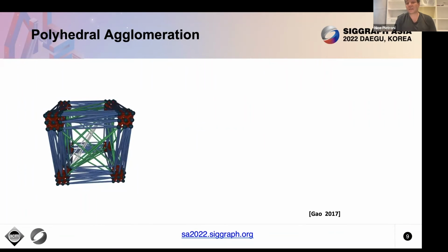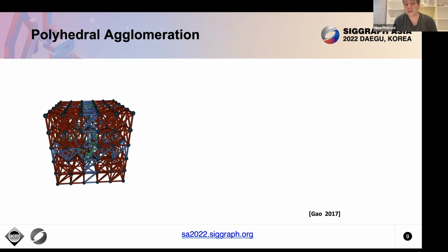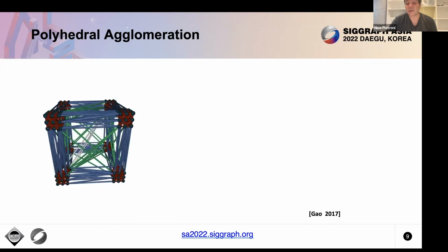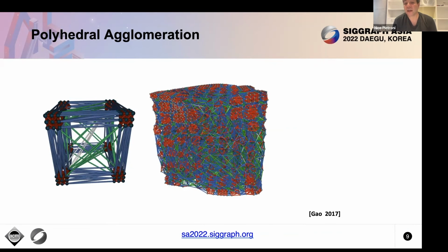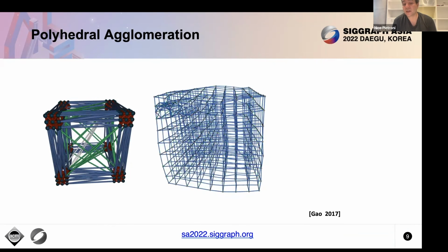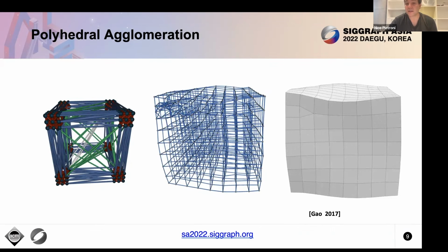In the end, you get this extremely deformed, tessellated tetrahedral mesh on which you can do a set of local operations so that you can extract your hex mesh by collapsing the tets which are not nice. And then you can have your final hexahedral meshes. Obviously, you can see here there is a triangular face, and that's exactly what happens with X-dominant meshes. So they have elements which are not hexahedral.